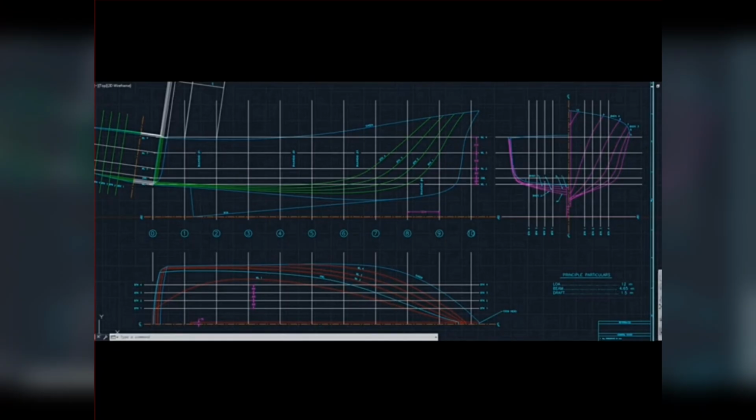In the profile view, you also see horizontal straight lines, and these are water lines. Of big importance is something called the design water line, or DWL. This is where the vessel is expected to float when she is loaded as per standard and when she's in calm water.